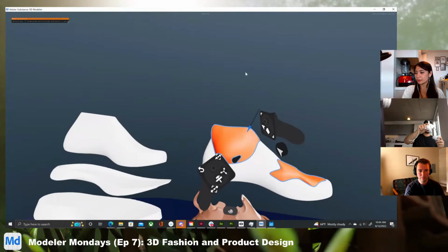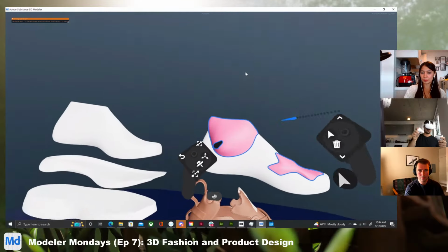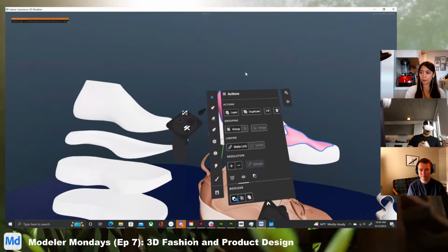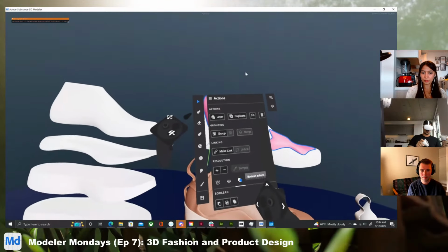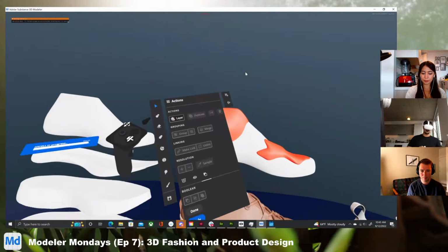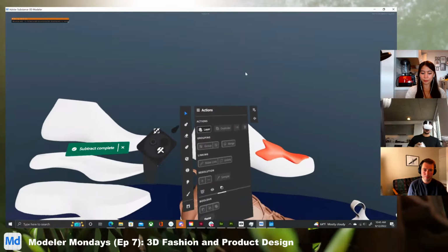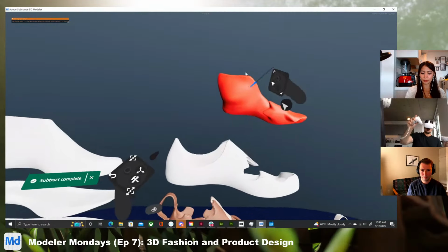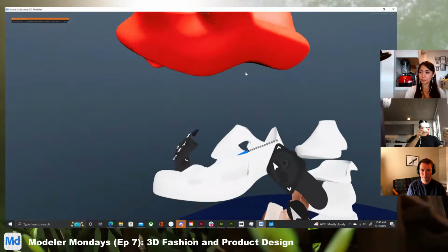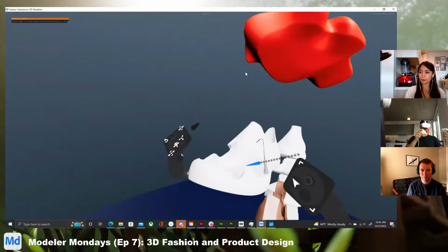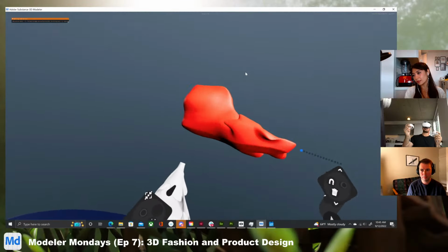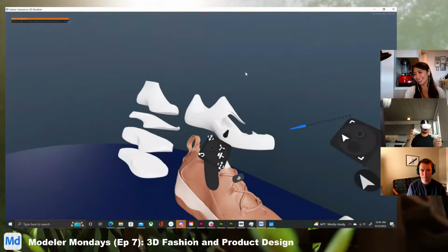So I'm going to select this component here. I'm going to hit the edit or action mode, and down here, the little box-in-a-box icon in the bottom left-hand corner is the Boolean subtract mode. If I hit apply and let it think for a bit and move this one out, what remains is that internal shape in that form there. All that surfacing that would have been really hard to do with just the base clay brush, I'm able to get just by taking two lasts. This looks really weird, but I don't need it anymore, so I can delete that.